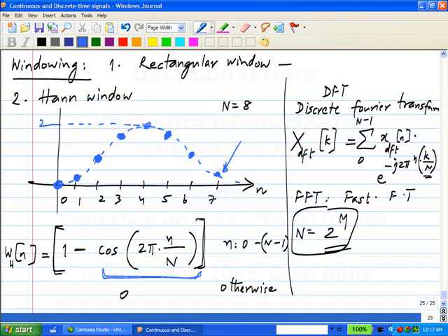And if you calculated this is 0 and this is n minus 1. And if you calculated the nth point, it would be 0. Okay. So the last point is not 0. So it starts from 0 and ends at something close to 0, but not 0. And if you calculate the next point, it would have been 0. That's how the Hann window is defined.